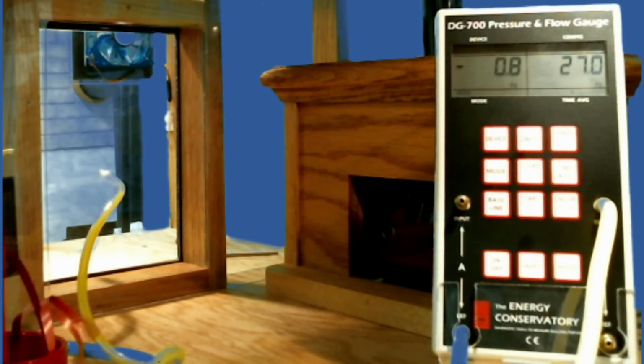So in that case, maybe instead of undercutting the door so much to relieve that pressure, we might reduce the amount of airflow by putting a damper in the attic. In this case, it was an attic, and you put an adjustable damper in the attic, not on the grill in the bedroom itself, but in the attic where it comes off that main trunk. And so in this case, you can see the house is negative there.